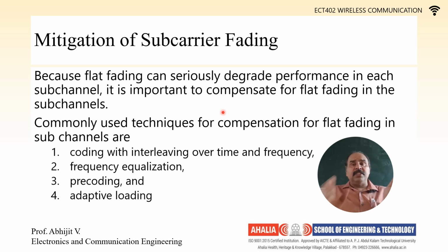The answer is, the commonly used techniques for compensation for flat fading in subchannels are: coding with interleaving over time and frequency, frequency equalization, pre-coding, and adaptive loading.